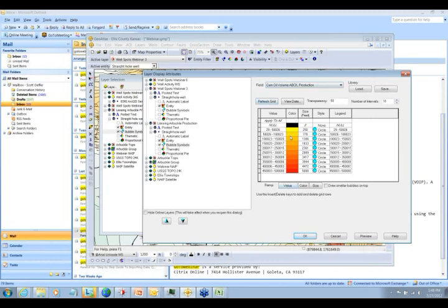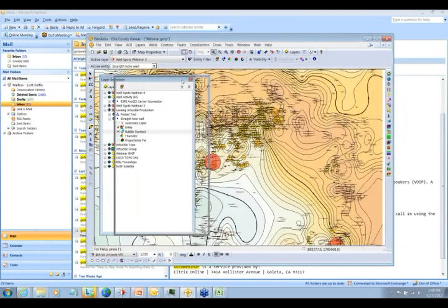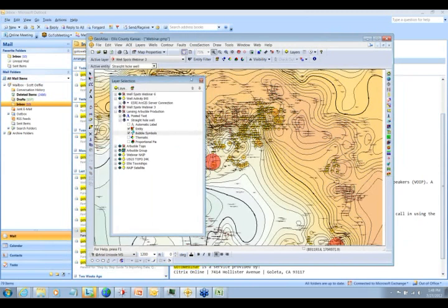You can color ramp any way that you want to. You're able to view the data available. You're able to select the range of data available, ramp up the color, ramp up the size, change the number of intervals. All of this is basically a very, very robust way to create a bubble map. And pies also. So pie maps work just as well. Cancel out of there.